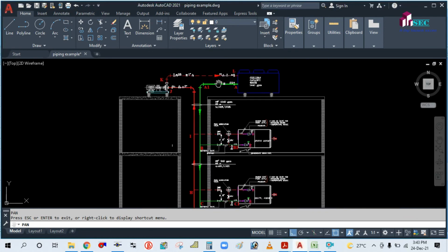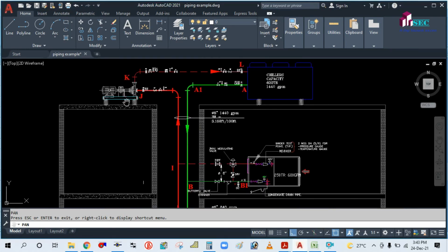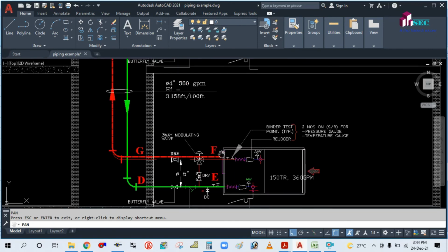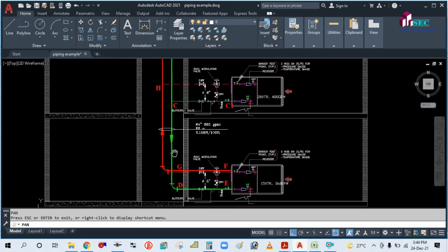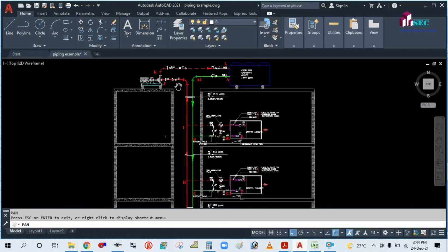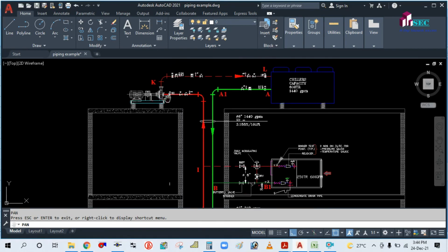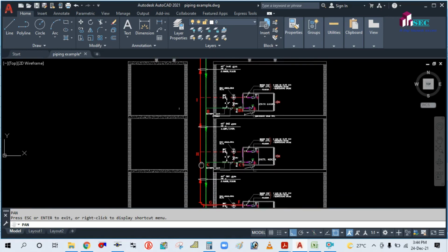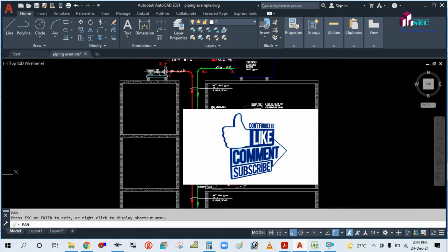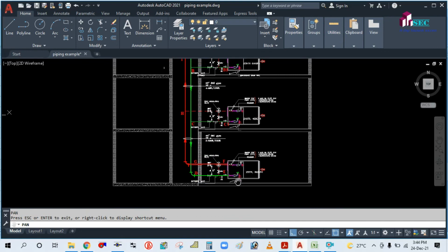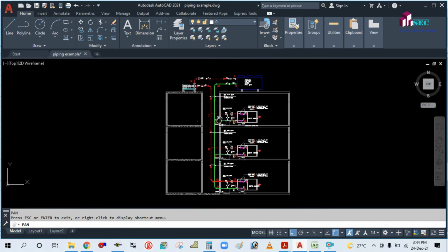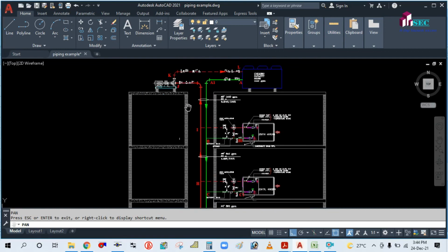So with the same riser diagram we will see what will be the pump head and what will be the critical route. So in the fan selection there will be the critical route. So to select the fan we are looking for the critical path or longest path. Here also in the pump head calculation we are looking for the critical or longest path. So in this you can see here, critical path is this one. Okay, your pump pushes the water up to this last AHU and again returns back to the system. Okay, so how to calculate this pump head we will see in the next tutorial.